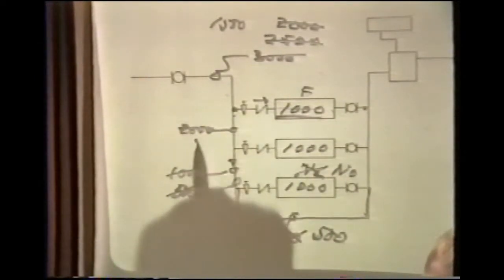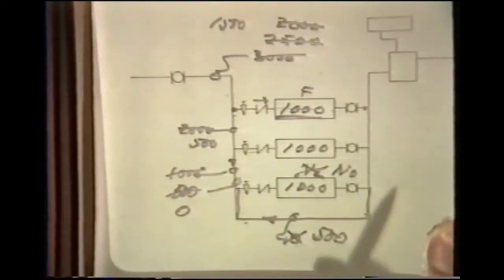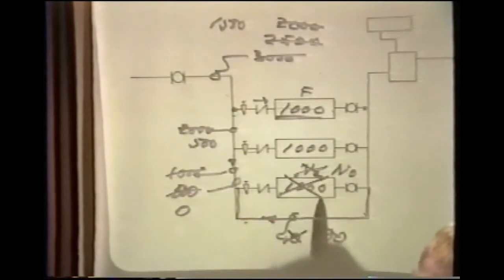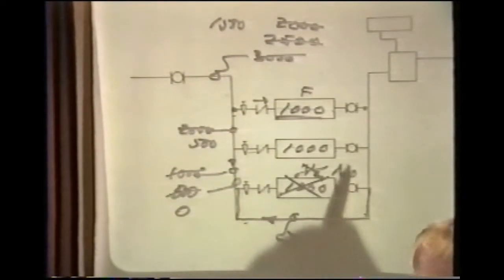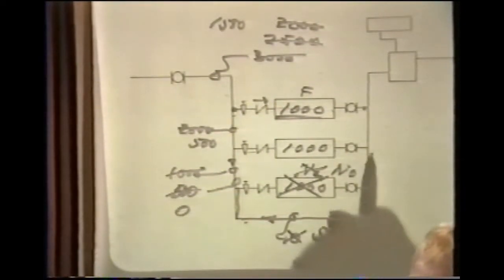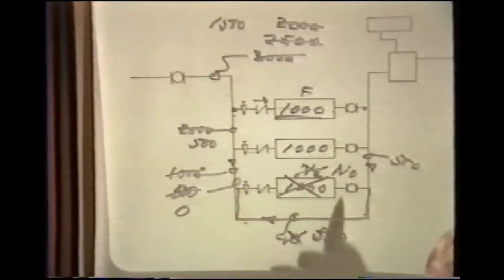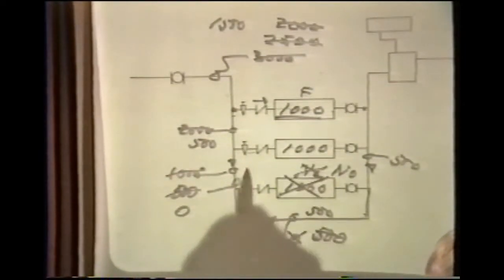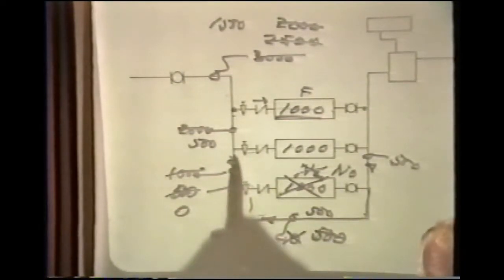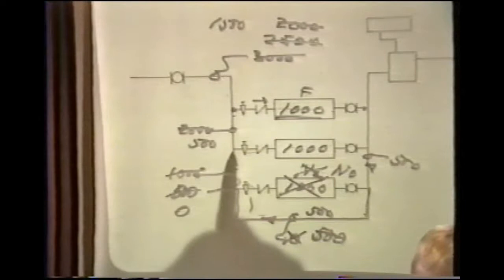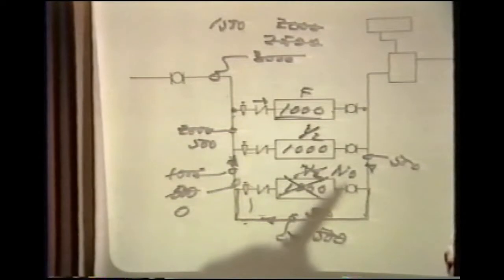We now have 500 GPM in the piping proceeding to the second chiller. The third chiller is now off the line, and because the second chiller provides 1,000 gallons per minute flow rate, we are now in bypass with 500, and again proceed to the intersection backwards now to this point, where 500 GPM of leaving chilled water is mixing with 500 gallons per minute of supply of return water. So this chiller now goes on half load.